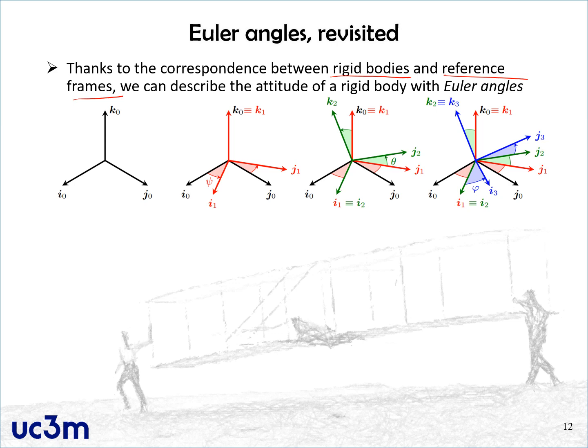We will basically introduce 3 Euler angles, right? Usually by the name of psi, theta, and phi. And we will have 3 simple rotations in a prescribed order to go from the orientation of our reference frame S0, wherever we are working, to the reference frame SB of the rigid body. Okay.